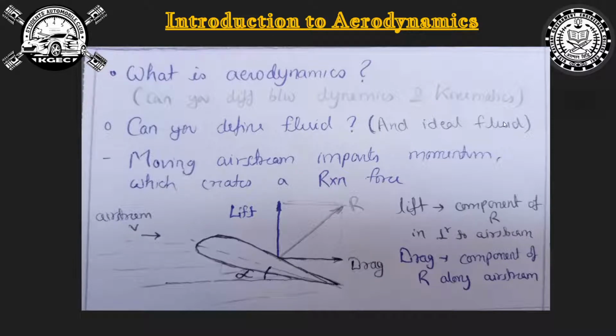And the compressibility we have talked about depends upon the speed of the flow. By saying the flow speed is high, I mean it is high with respect to the acoustic velocity. This ratio, the velocity of flow to the acoustic velocity, is called the Mach number. If the Mach number is high, generally taking 0.5, then we have to consider the compressible effect, otherwise we neglect it. Okay, so that's an ideal fluid.